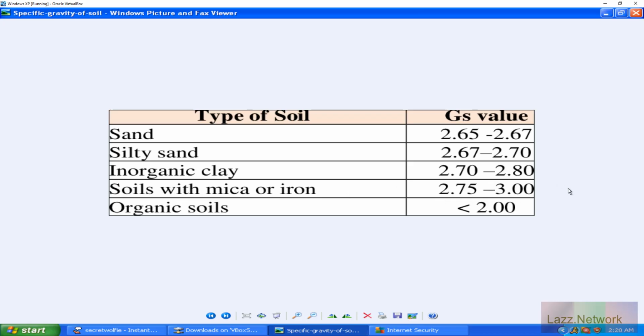Granted, for the specific gravity of soils, this test method doesn't cover performing specific gravity on fine aggregates and coarse aggregate, or asphalt or anything like that. That's a whole other test method, and the procedures are done vastly different for that.